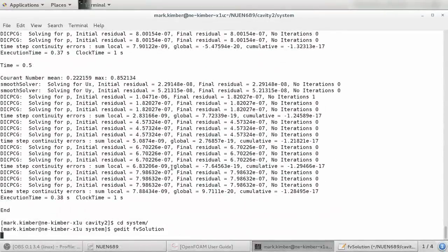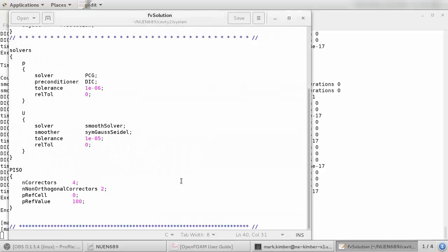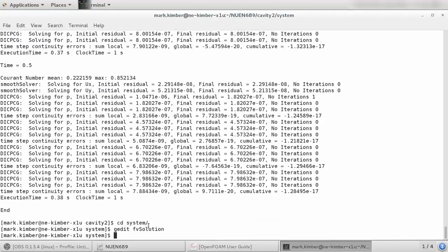And this is again not going to affect the accuracy of the solution, it just affects the path to the solution. In this case, it's such a quick simulation, it doesn't really matter, but in other scenarios, it might be advantageous from a convergence standpoint to change these numbers to get solutions quicker, but it shouldn't affect the overall accuracy. The discretization scheme is going to affect the accuracy. So let's put this back to 0 and 2. It's back to 0. Okay.